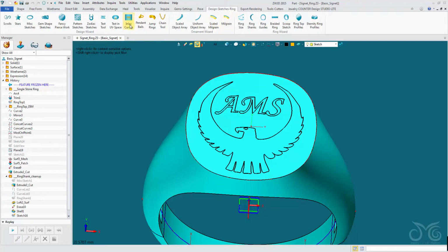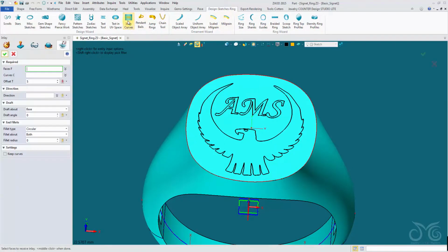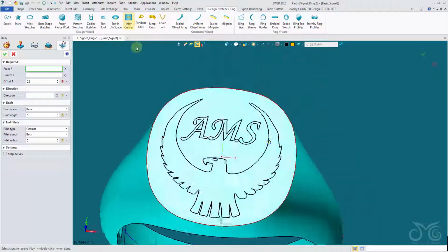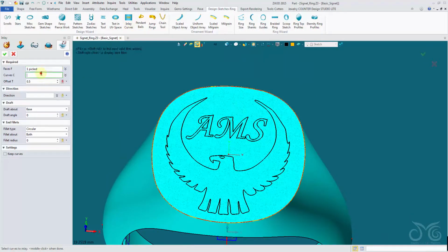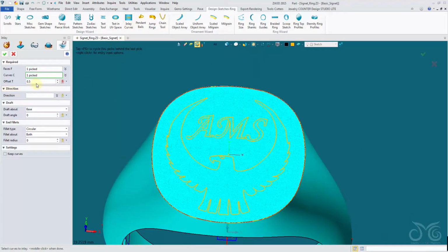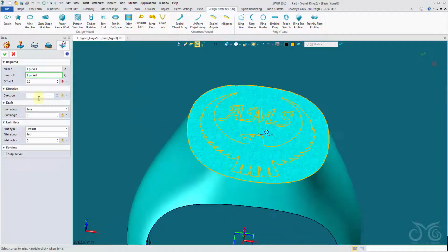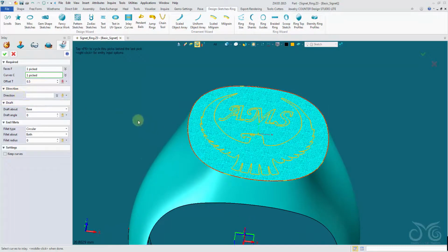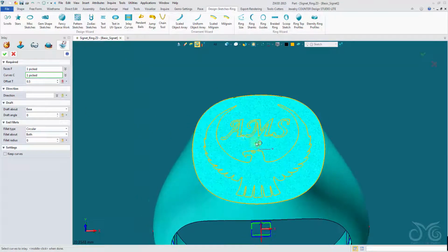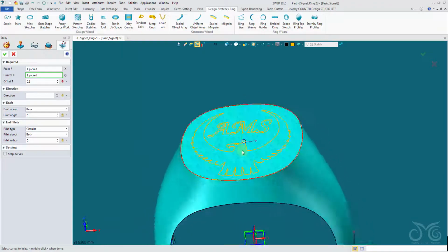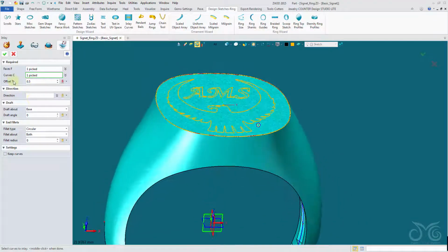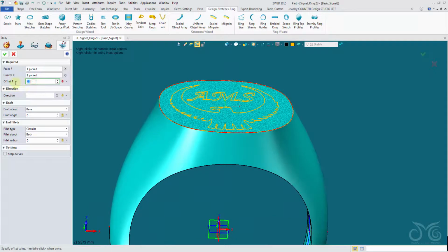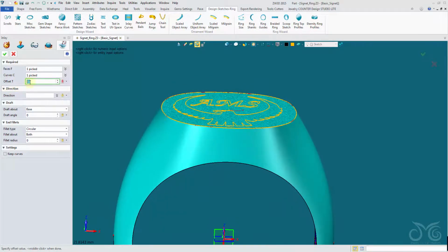We have the JCD inlay curves command. Same thing. Pick our face, pick our curves, pick it as a sketch. Our direction is by default normal to the face we've picked, so in this case it will be Z. We can always define a direction, but if we leave this blank, our offset, if it's positive, will be coming out an emboss, negative an inlay. Confirm the operation.